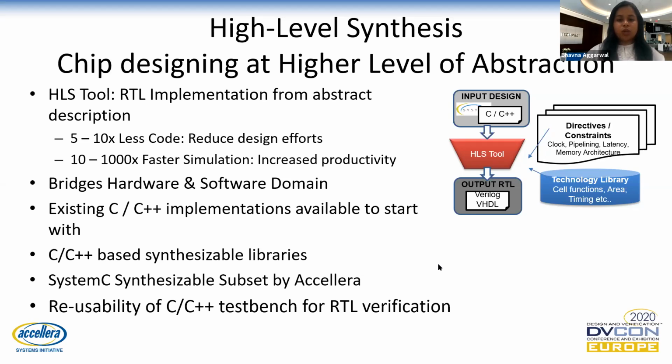These constructs ensure that the software implementation can run through a tool called a high-level synthesis tool and automatically extracts an RTL out of it. The Accellera community has also come up with the synthesizable subset of SystemC, using which we designed a SystemC IP encapsulating the SOBEL algorithm.